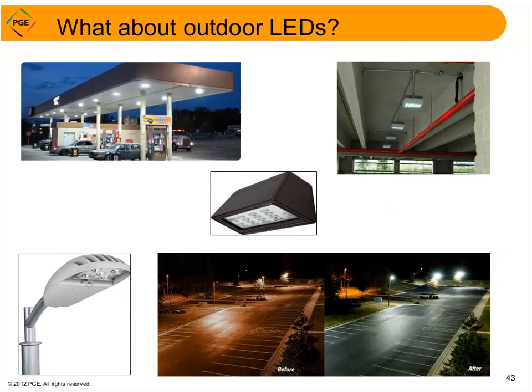Because of limited time, I'm not going to go over outdoor LED fixtures in detail. Some are cost effective now and some are not. Again, the high cost of the fixtures is the main obstacle. In general though, LED outdoor lighting provides even light distribution, long lamp life, and energy savings of 50% or more. They also work great with controls.